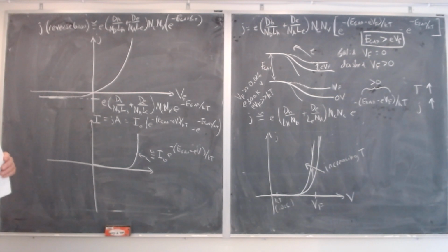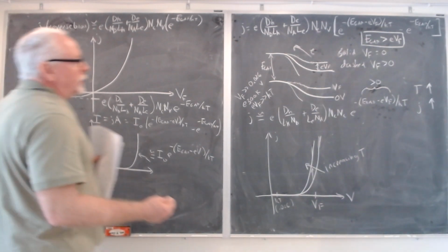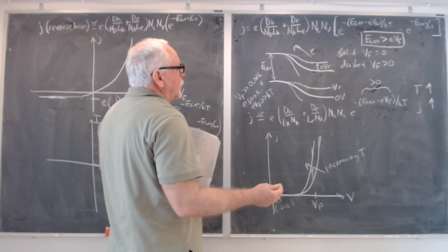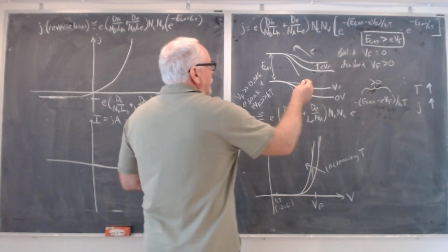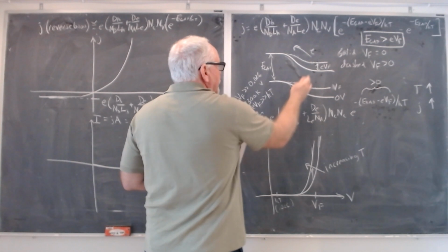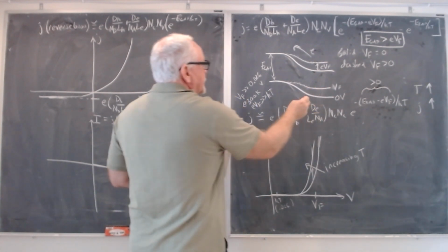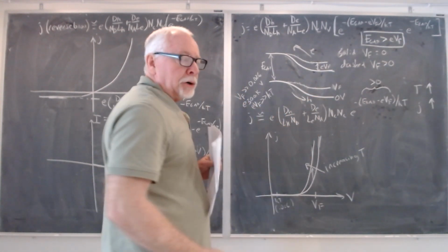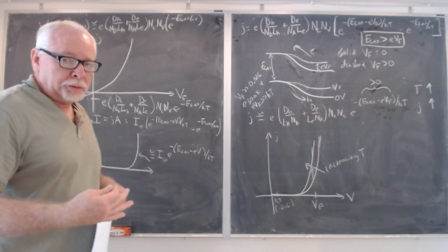Now, we're going to do solar cells, but just very briefly. If we get to the end of the course, we can come back and go into solar cells if you want. Now, we can refer to this diagram here. Remember, and I'll get rid of the reverse bias here, when we forward bias it, we get electrons and holes, and that constitutes our current, which I'm going to start referring to as dark current.